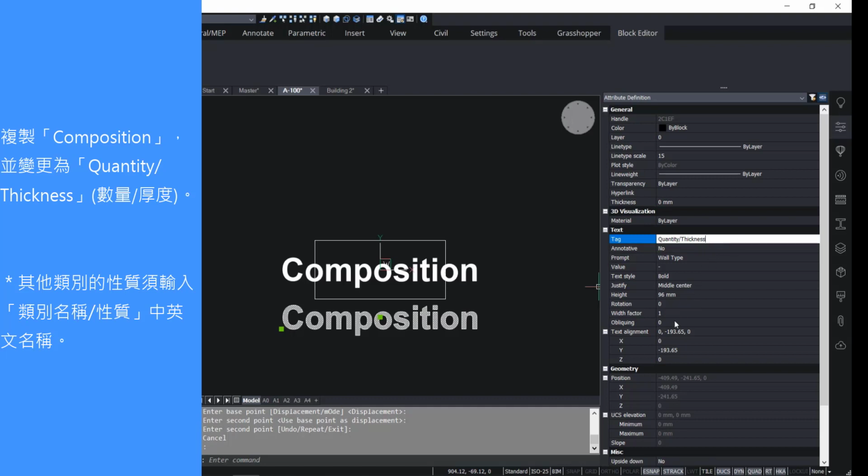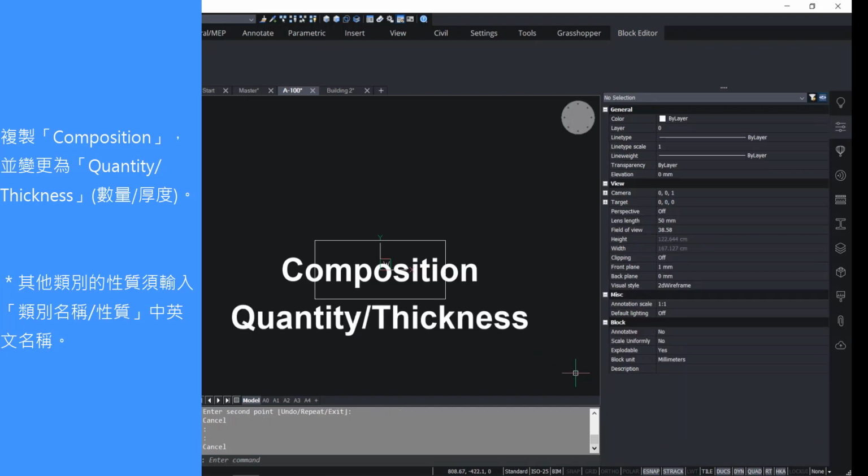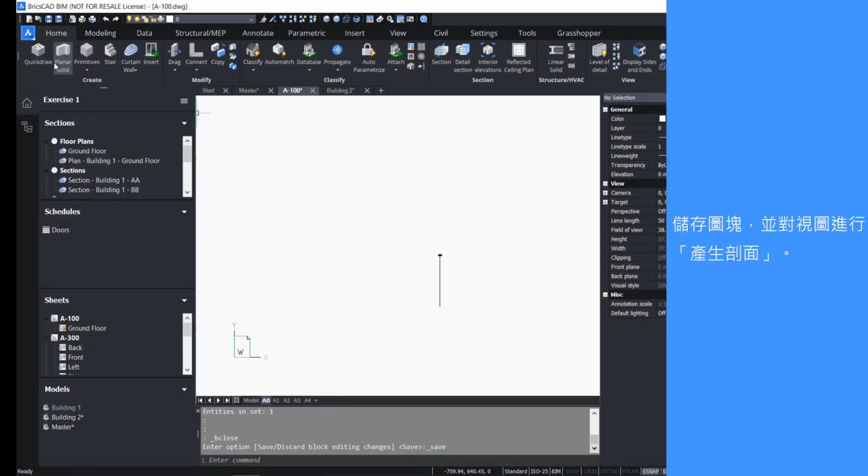And then if you want to have, for example, text alignment X, like this sub value, you should type in text alignment, semicolon, and then X, for example. So the syntax you can view in your handouts with a bit more explanation, but in general you have the property category and then the property name itself. If no category is specified, the BIM category is assumed. And you can now delete the rectangle as well and save the block here.